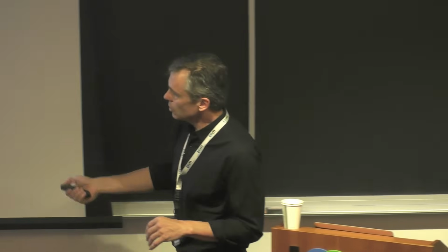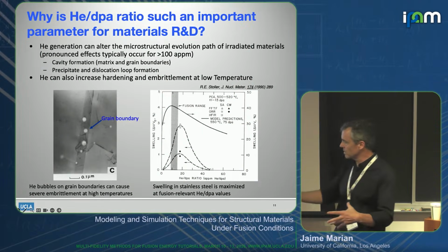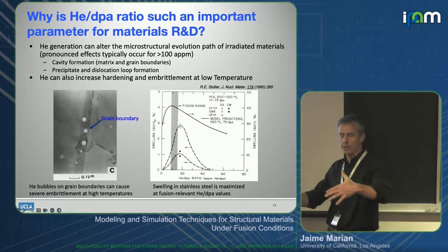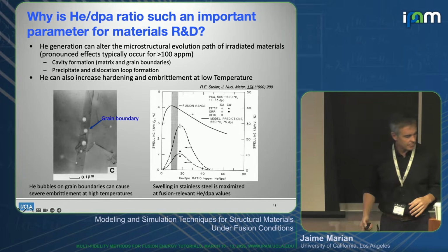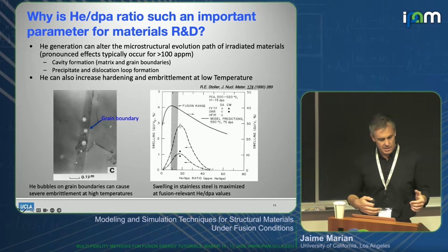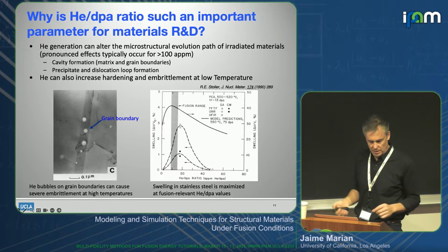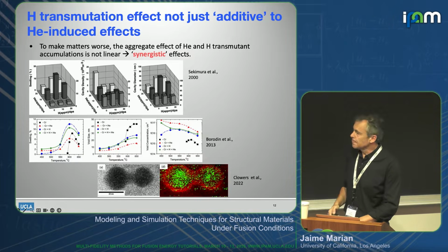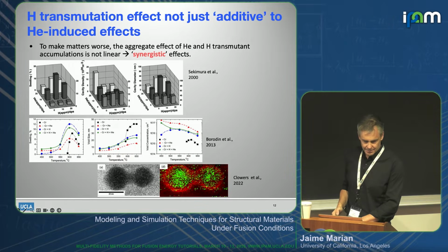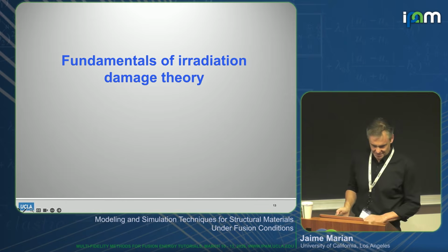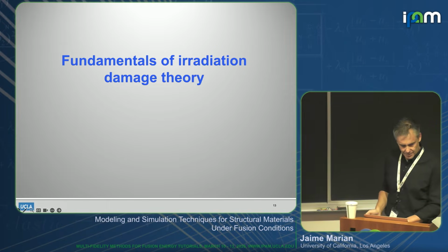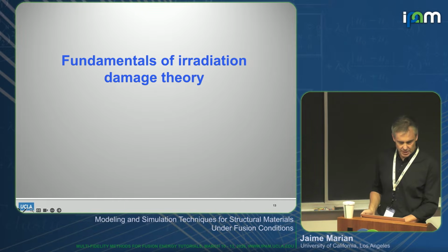Here you see the effects of helium, how they form these bubbles, and these bubbles will eventually coalesce and give you like a pillow, like a cushion between grain boundaries. And they will lose cohesiveness, and they will separate, and you'll have zero strength in these materials. All right. Enough bad news. Let's move on to something different. Okay, let's go to something a little bit more fundamental, theoretical.